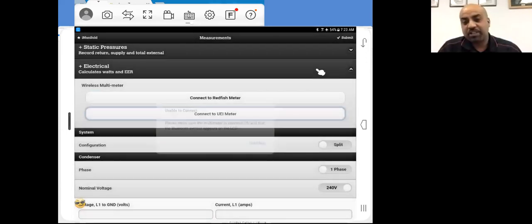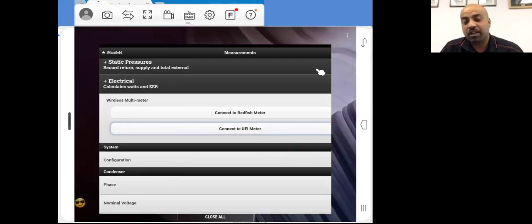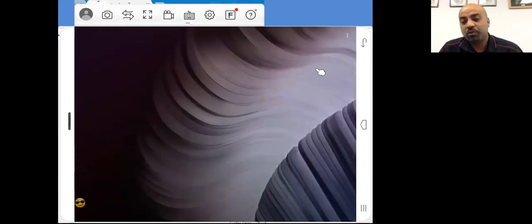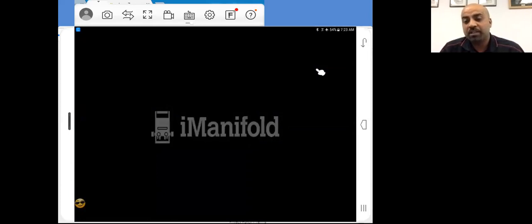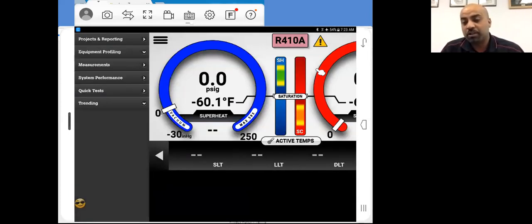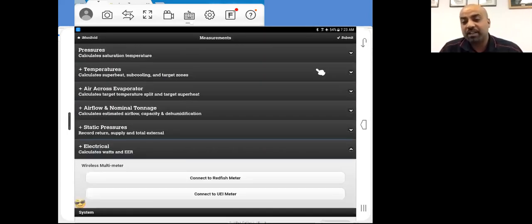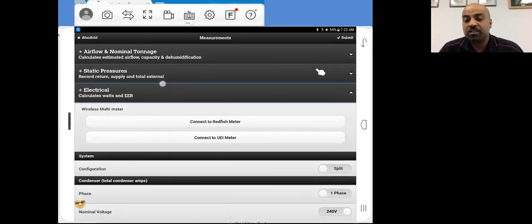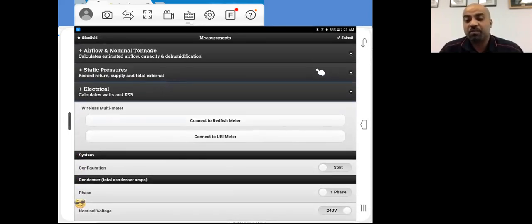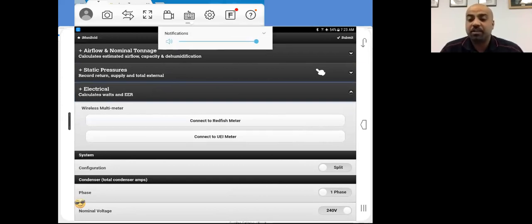And the other thing is with the DL429, I know we only have the voltage and amps right now using the current software, but the DL429 as well has its own app that's available both on the Apple Store and the Google Store that allows you to record the data, store the data, and graph the data as well, and export it right from its own app. So if you want more than just voltage and amp functions, whether it be temperature, capacitance, or any other features that you're using on the clamp meter, you can use its own app to log as well.